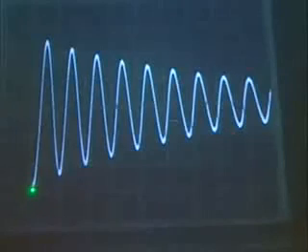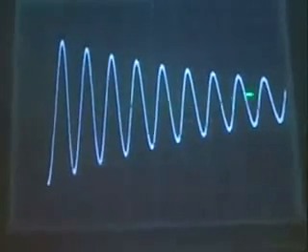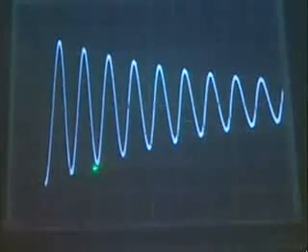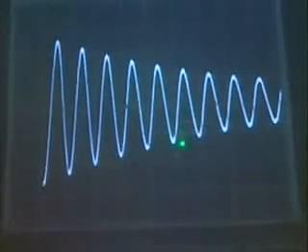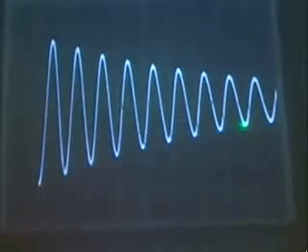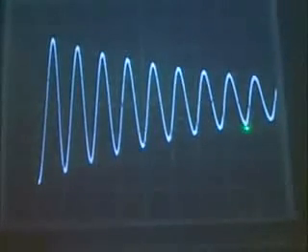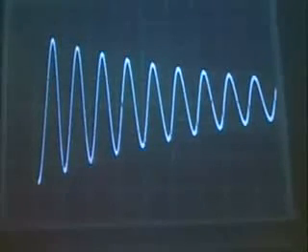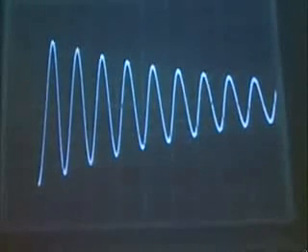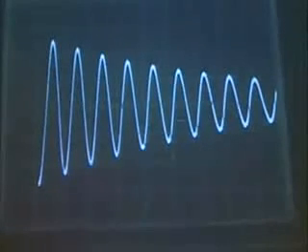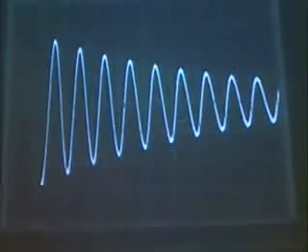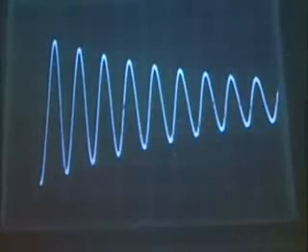So Q is 0 is on the left side of the bottom. This is again fully charged, Q max. And now we go 1, 2, 3, 4, 5, 6, 7, 8. And the amplitude now is roughly the same what it was before when we had 6 oscillations. So you see that this works like a charm if you do it with an LRC circuit. Really quite remarkable. It's a dying oscillation, and the damping is the result of the resistor, which is dissipating energy.